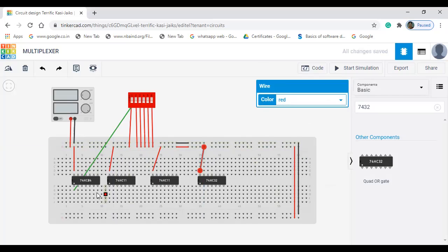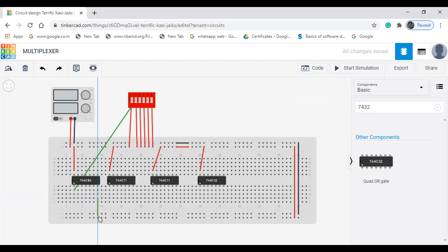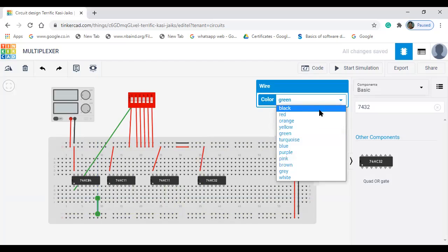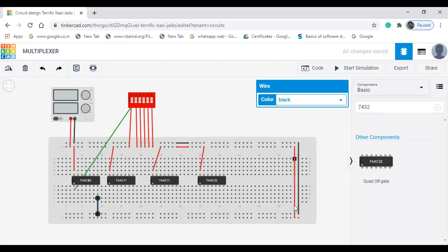now all 7th pin should be ground. Okay, so what we are doing is, this is 7th pin. We have said bottom can be taken as ground. Okay, because we have shorted top and bottom, so this negative portion you can take it as ground. So we are just connecting this, all 7th pin, I'm just connecting to the ground.